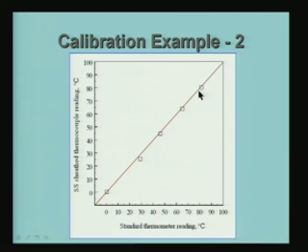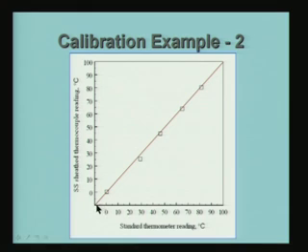It is good practice to choose 4 or 5 calibration points or temperatures, in this case temperatures. It is valid for any instrument. If I am using a voltmeter, if I want to calibrate the voltmeter, I must calibrate not at the extreme points. Extreme points are not reliable. What I have to do is take 10%, 30%, 50%, 70, 80, like that. We have to take several points in between the minimum and the maximum, and then use the calibration if it is a voltmeter. If it is some other meter, exactly the same thing.